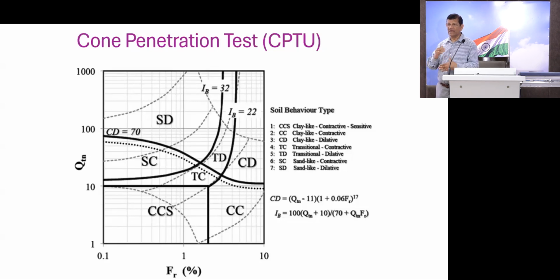The drained and undrained strength, we will discuss more when we look into the case studies. We'll see how the drained behavior and undrained behavior is the key issue in deciding whether the dam is stable or not. Initially, when I was reviewing the data, before 2000 most of the analysis for the design was done using the drained strength, because that was the assumption.